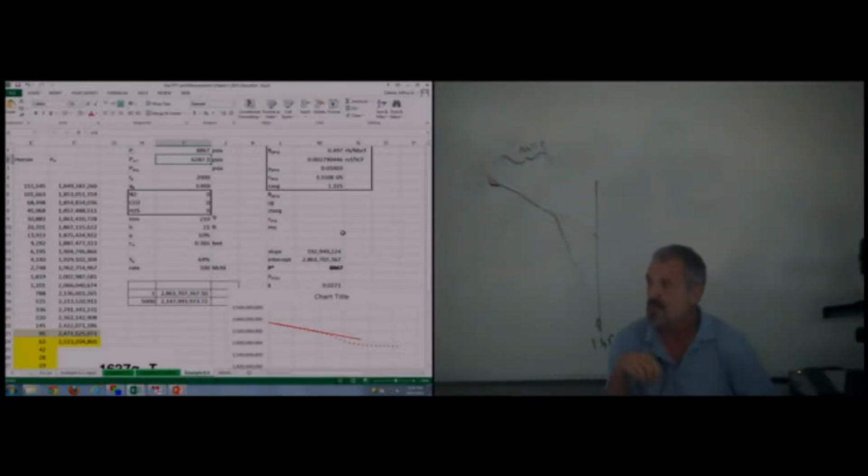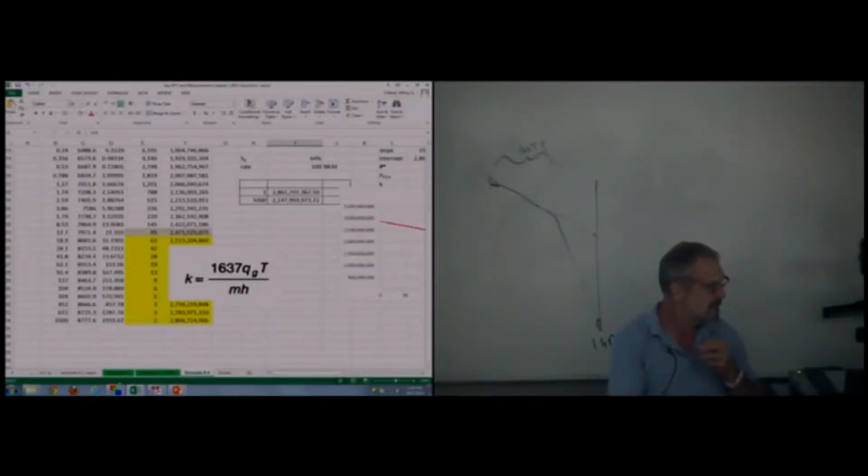That's why I thought it was blasphemy that they told me the initial pressure was 9,000 pounds. This test is about trying to determine what the initial pressure is, but you have to make some educated guess. If I just got this data and didn't have the textbook number of 9,000 pounds, I would have probably taken the maximum recorded pressure, 8,776, and maybe added 10% to it, as something to start with.